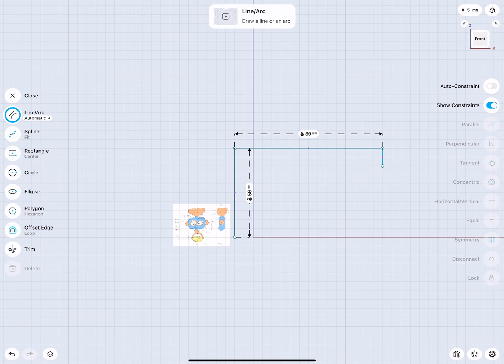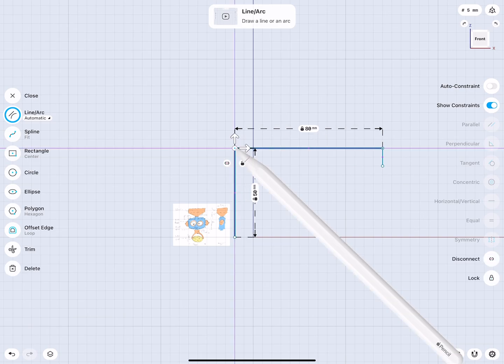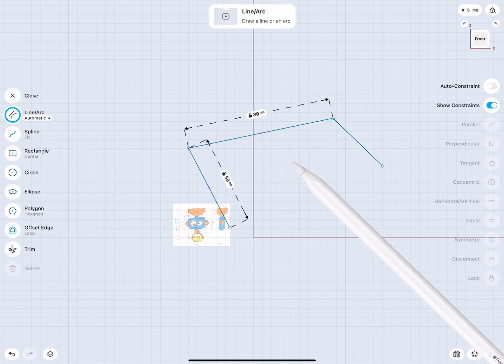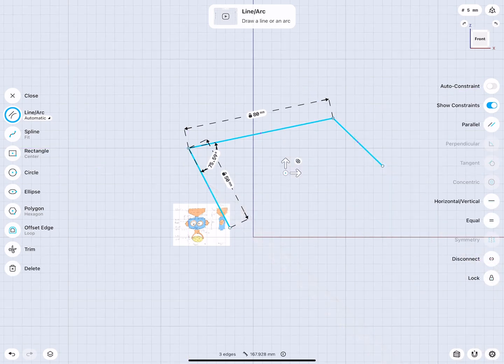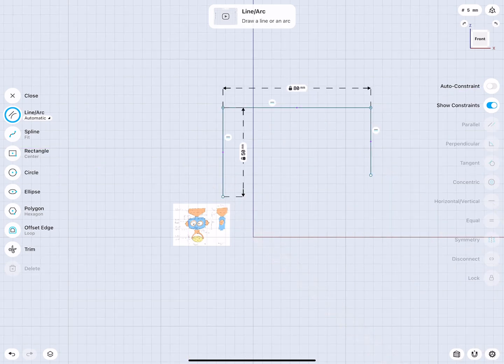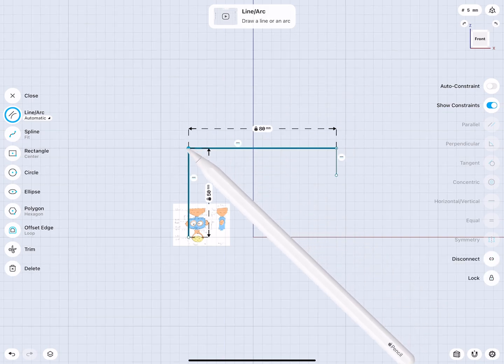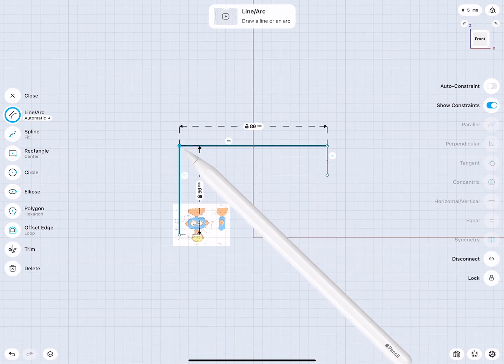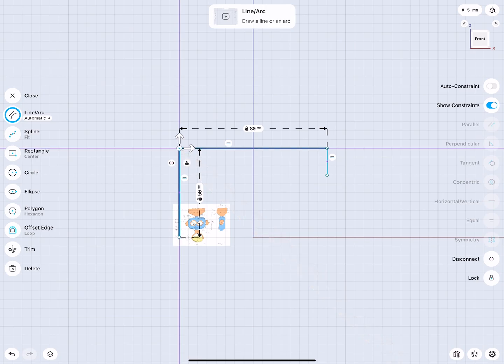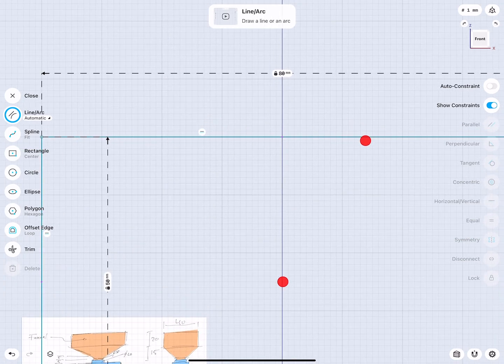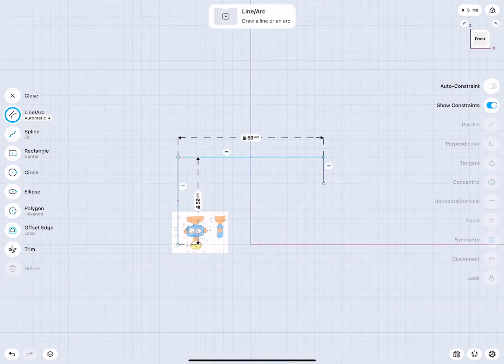Since I am sketching here first, let me finish this. I would like the sketch to be perfectly centered. So I can bring this over. Maybe I should select all these lines and first give them the correct vertical, horizontal constraints. There we are. And because I do work with the grid, via grid snapping, you see the midpoint of my line is perfectly centered. I can actually do a little trick.